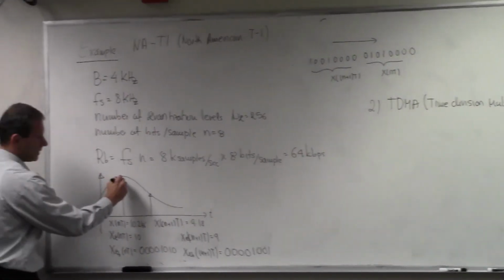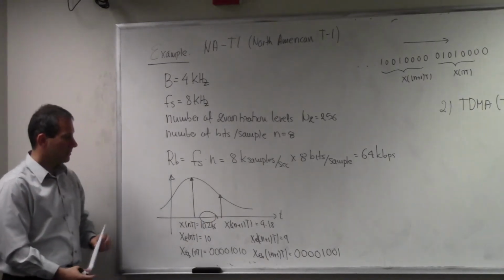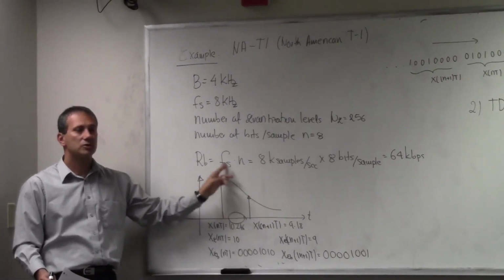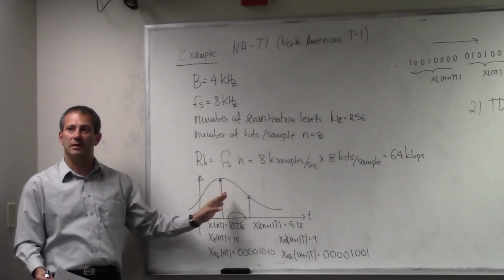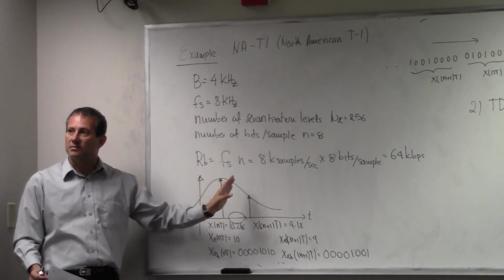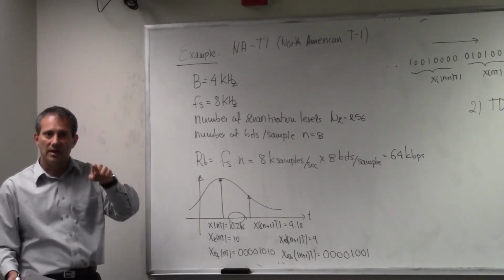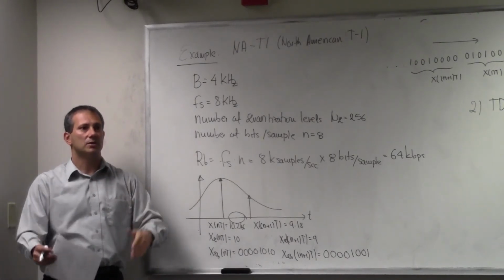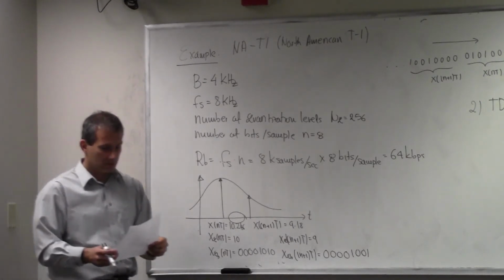You can see that I have this value, and then here I'm not transmitting anything, or I get rid of this whole portion of the signal. So the principal idea here is I can interlace multiple signals in time and use the same line to send the multiple signals and have them share this particular line.